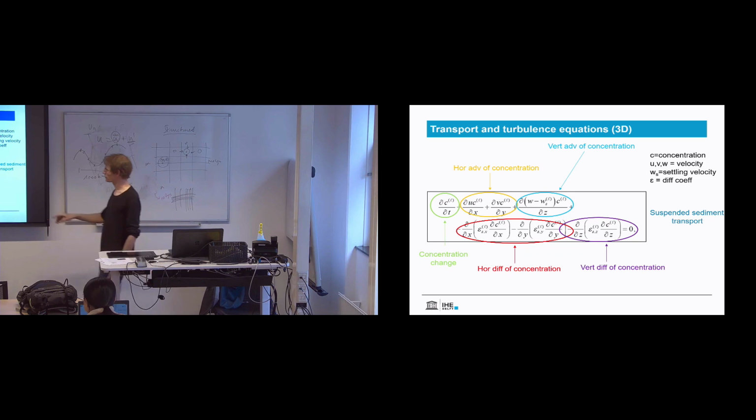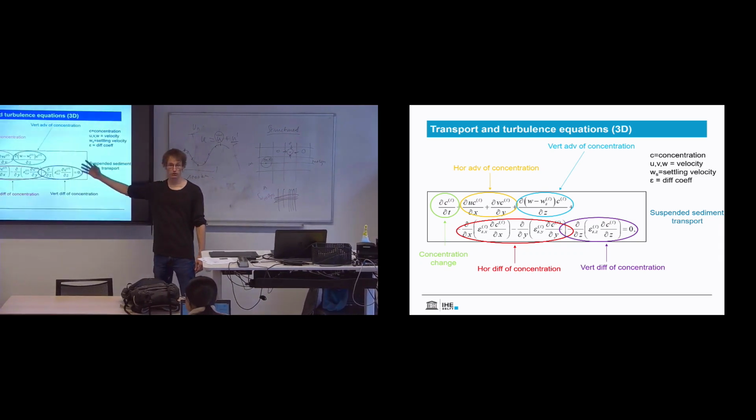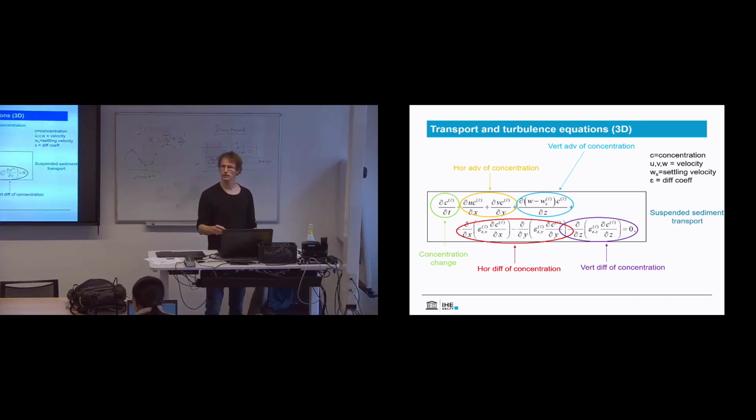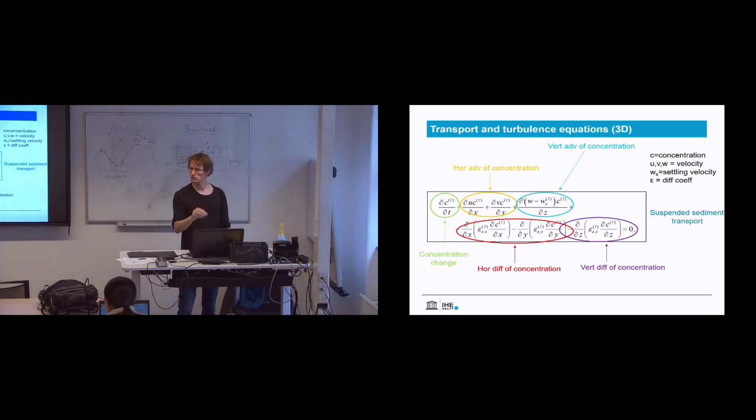So if you have vertical diffusion, which we can calculate with our K epsilon model, for example. If we have the K and epsilon, we can calculate the vertical diffusion profile. That is a factor times k squared divided by epsilon, I think, from the top of my head.